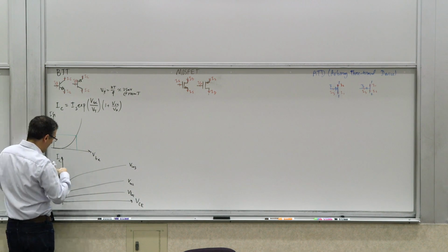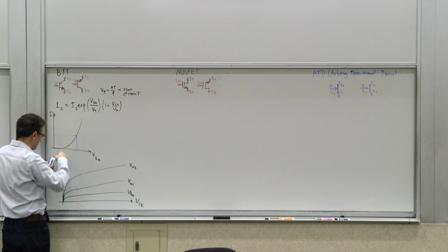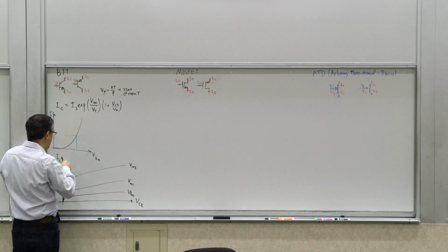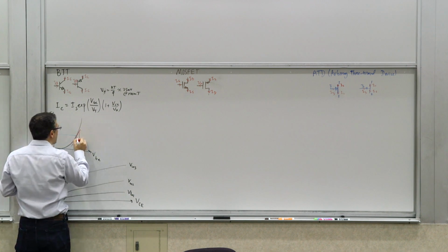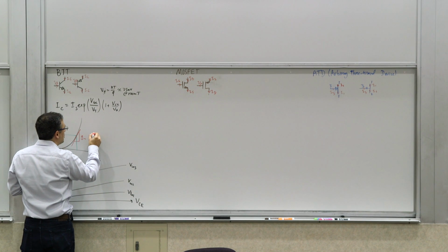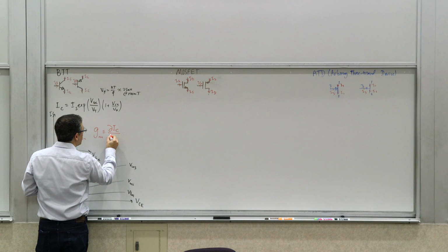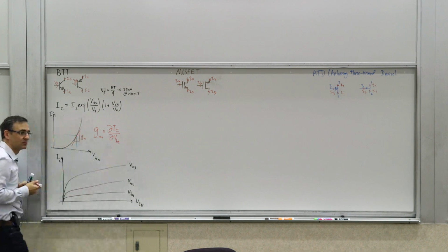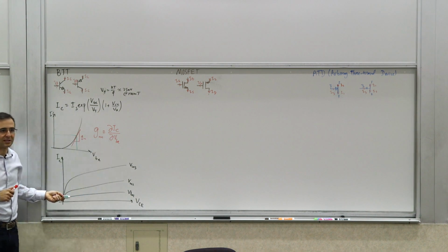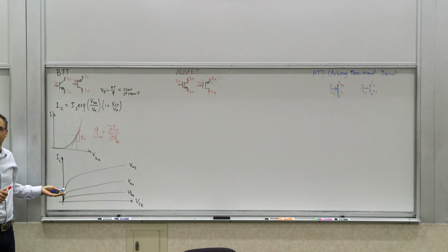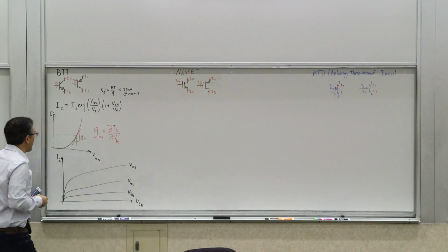What you have is that if you have fluctuations in voltage here, it corresponds to fluctuations in the current. And the ratio of those things, again, we've done this before, so we're going to do it quickly. We define that as the GM. So the GM is really defined as dIC to dVBE. And the reason we show them with partial is that it's also a function of VCE, for example. So there's more than one variable here. So, okay, that's what that is.